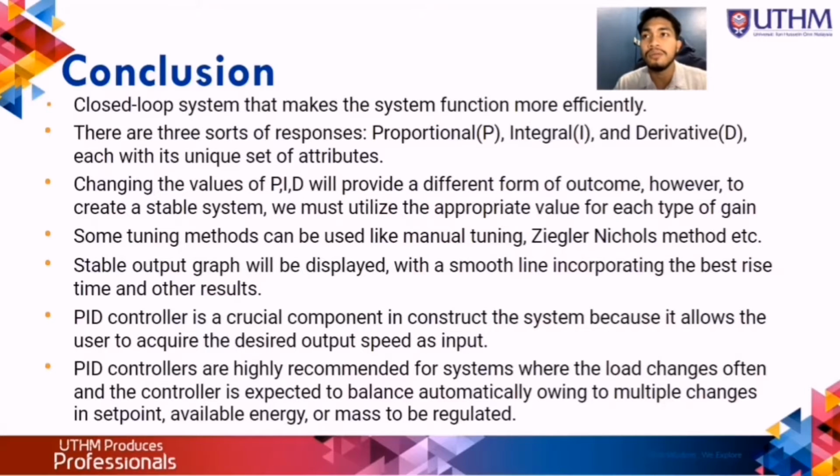Thus, there are some tuning methods that can be used to get a stable system, like manual tuning, Ziegler-Nichols, etc. As a result, a stable output graph will be displayed with a smooth line incorporating the best rise time and other results. As for designing the motor speed system, the PID controller is a crucial component because it allows the user to acquire the desired output speed as input. PID controllers are highly recommended for systems where the load changes often and the controller is expected to balance automatically owing to multiple changes in set point, available energy, or mass to be regulated.